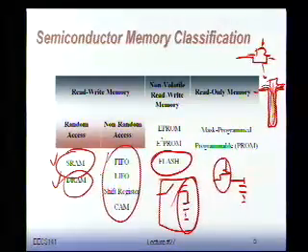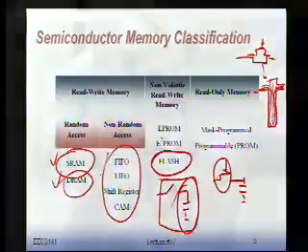Like, for instance, we have video memories. One thing about video is you take a video screen, and you write it row by row by row by row. It's very rare that you're going to randomly access a video memory. The data streams in, data streams out. So it's serial access, sequential access, so random access doesn't make that much sense. So fast video memories typically will have a far less complex addressing scheme, and as a result are simple. FIFOs are, it's really a FIFO, first in, first out type of structure most of the time.